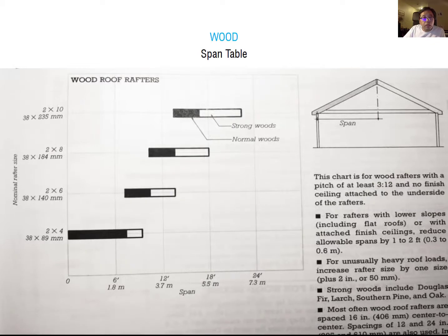It is the same as when you design the roof. It's a similar span scenario. This is the span, and when you want to make an angled ceiling, which is the angled roof, the gable roof, you need a rafter for the structure. This we can call the rafter, and from here to here, it is called the span. So depending on the timber product for the rafter, you can have a different span size.